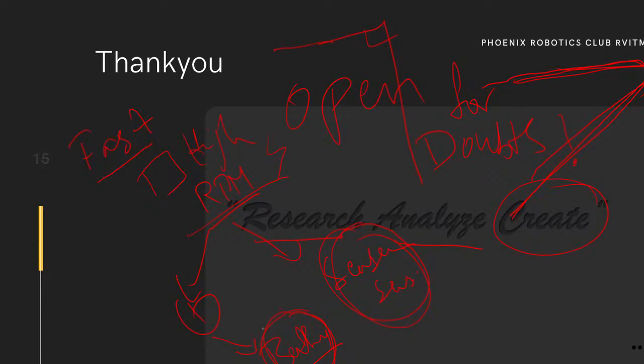And okay, you got a good battery and high RPM, but if the sensor sensitivity is very low, due to that high RPM, it can't have time to detect the path. Due to that RPM, it crosses over and goes outside of the path.